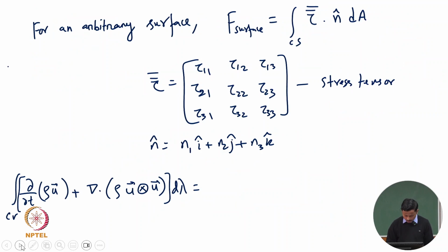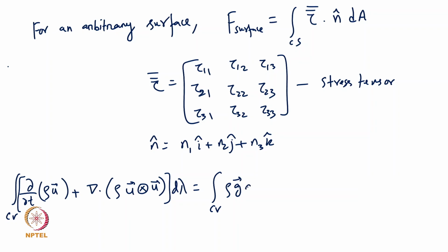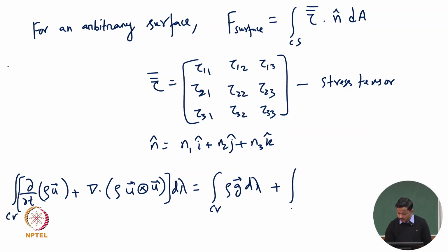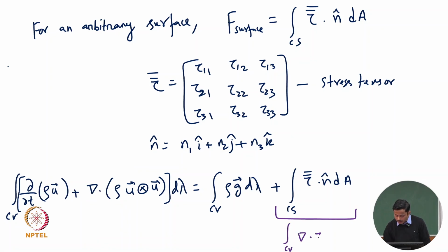Now we are expanding this force in terms of something that we understand, for example gravitational force or other kinds of surface forces. So now this is the control surface integral of tau dot n cap dA, and this can again be represented as a divergence of the stress, but the integral over now the control volume. Again the student might pause and guess what has been applied.